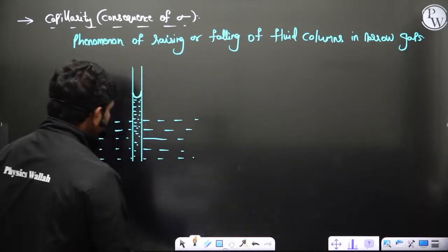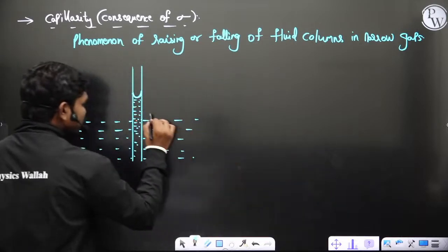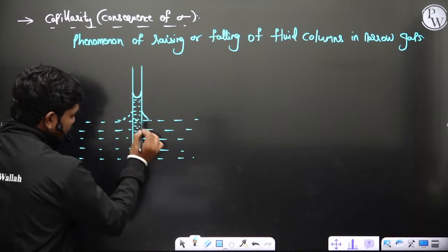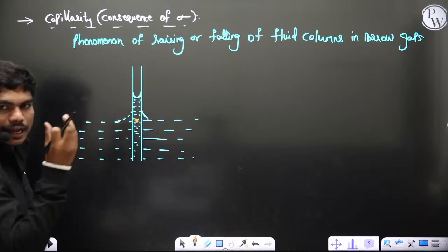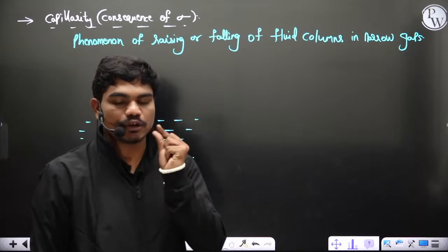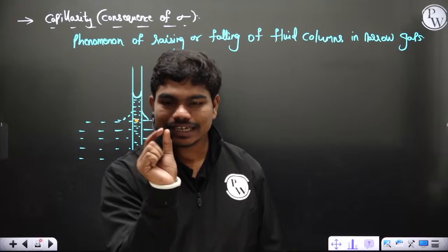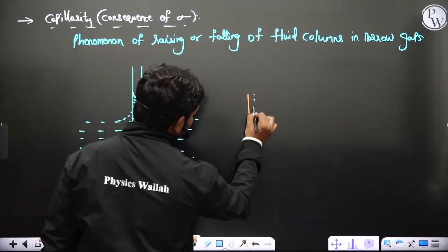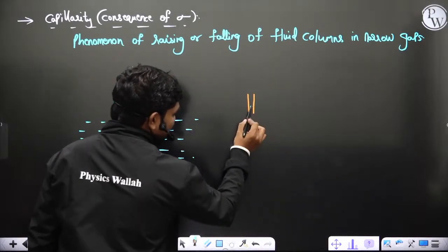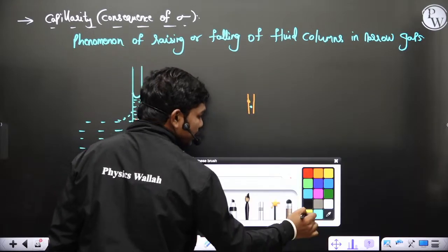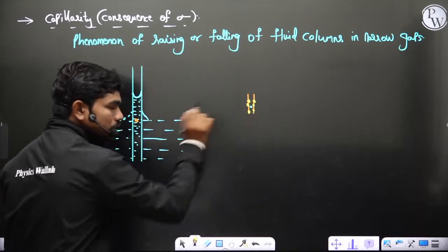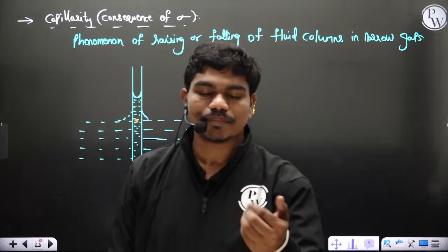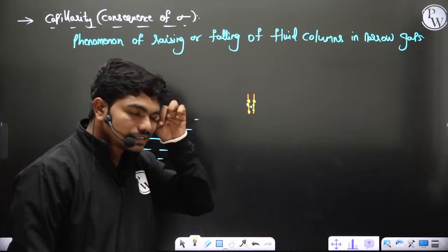Look, if you take a water molecule here in general, this curvature will be there slightly. Of course it's in general not seen with the naked eye, but you can feel this. Now if you take a particle at this location inside the tube, why do you see capillary only in small tubes? Whenever the tube is very small, whatever substance enters into the tube is surrounded by a lot of particles. If the tube is very narrow and some particle enters here, this particle is subjected to adhesion forces by many of the surrounding molecules of the other substance. All these particles are very close to that particle and they all exert force. But if the tube is sufficiently large, even though the particle comes there, cohesion and adhesion, pressure forces, all these things come into the picture. So that's why this phenomenon is generally seen only in very narrow channels.